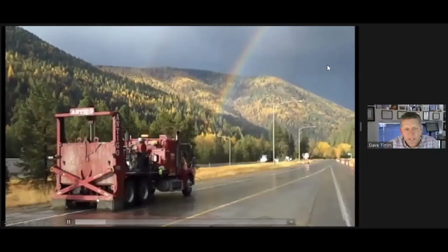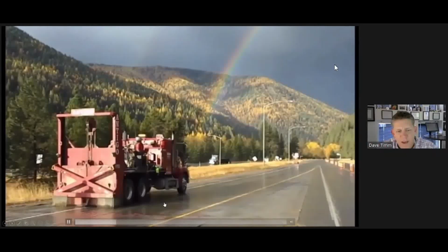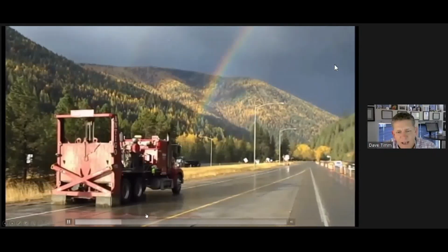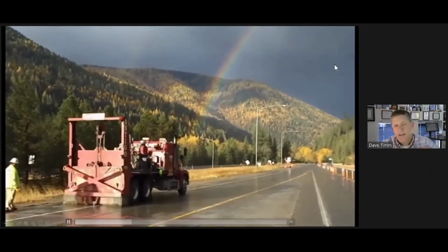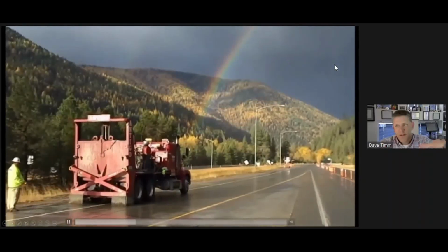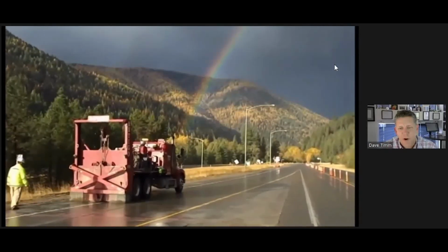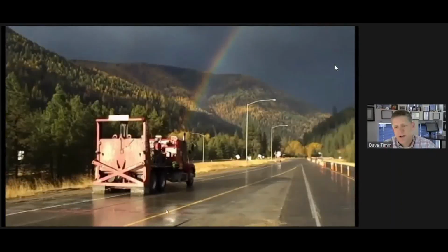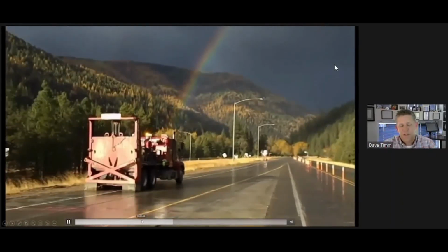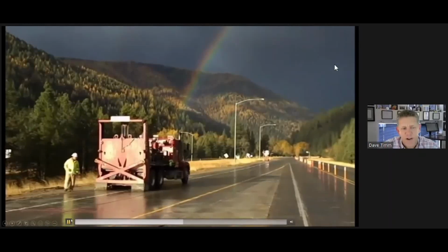As I said, it's a guillotine hammer, and there's a mechanism to raise and drop that hammer, and it fractures the slab, and it just marches along. Then we seat it back down with some rollers because the slabs may be a little bit uneven after we go through this process, and then we can overlay. But it essentially turns the concrete slabs into very short slabs that no longer have slab action that causes reflective cracks.